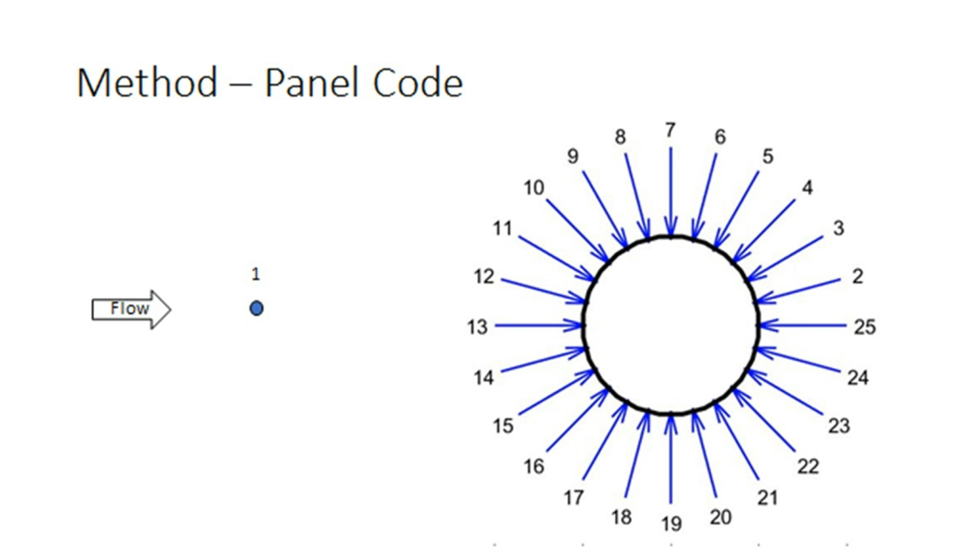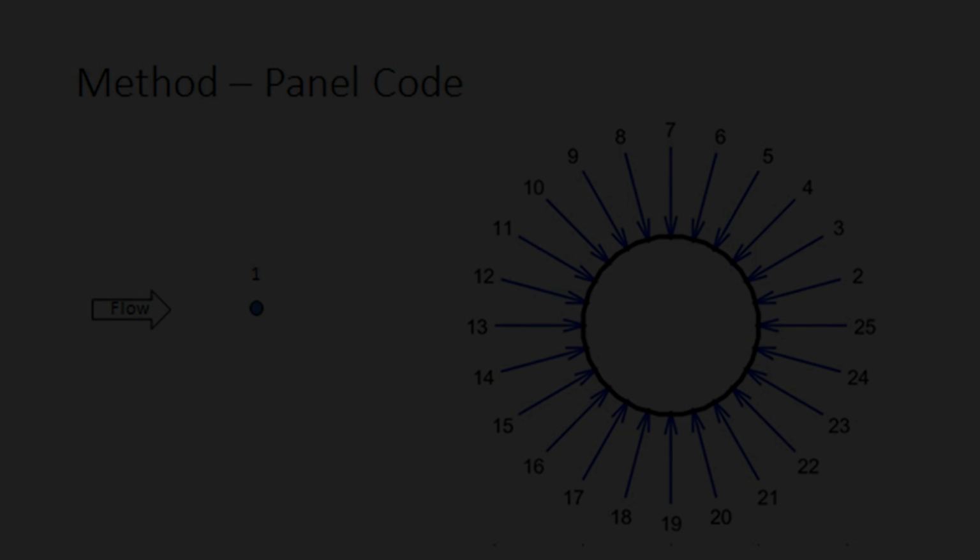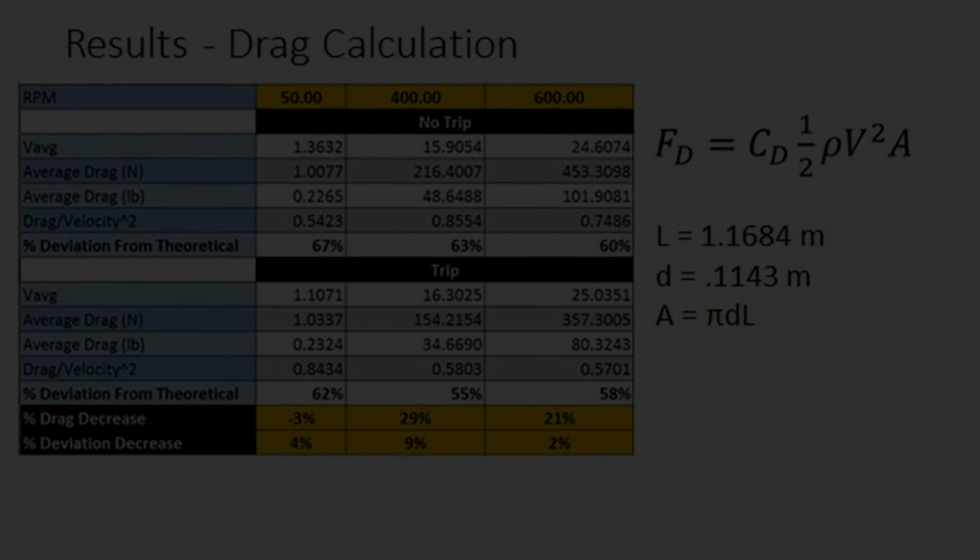In the case of the cylinder, the pressure values on the back side turned out to be negative, but remember that that assumes an inward normal vector. Therefore, positive drag should occur. Panel method is simply an experimental way to approximate a value that could be found mathematically using an integral.